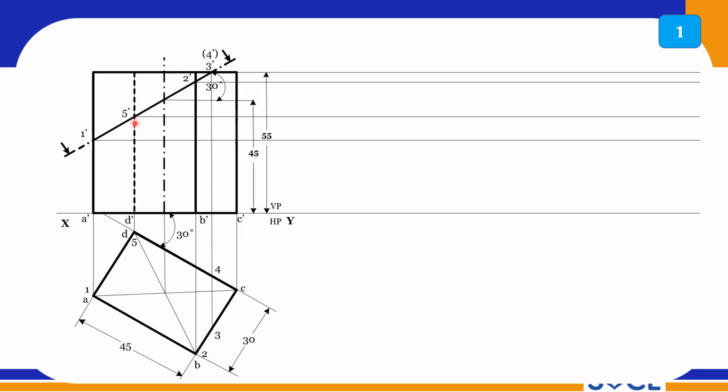I have to project them onto my development also, right? So now with thin lines from each and every point, you draw thin lines. These are known as parallel lines. That is why the method is known as parallel line development. And now you take some sufficient, convenient distance from this view, and start the development.